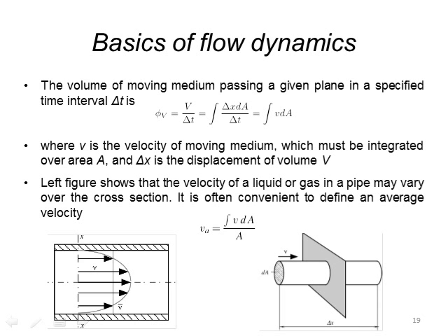So when we're talking about the flow velocity, we're always dealing with an average flow velocity. We're going to average it over the height of the tube in which we're measuring it. So V sub A, this average, is going to be the integral of the velocity times the differential of A, over the total cross-sectional area.